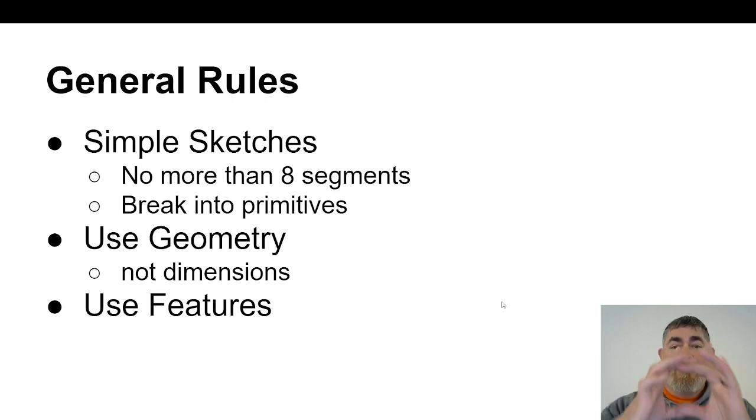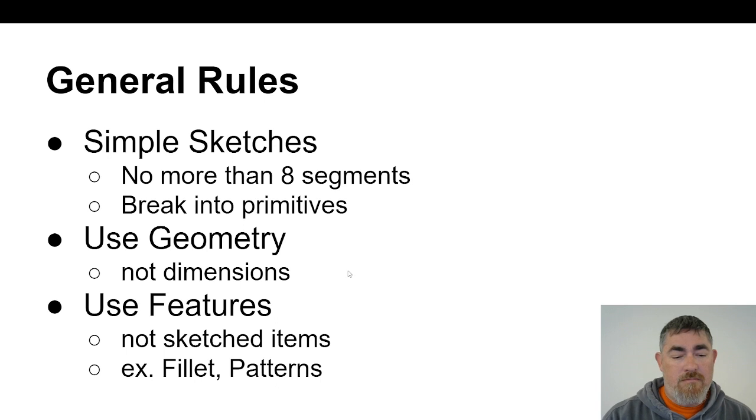Same thing with hole. Don't just extrude a circle, use the hole command. Now you have options to add chamfers, counterbores, threads, and not just to make an exact size, but make it a clearance size based on the standard. So instead of making a 1/4 inch hole for a 1/4 inch bolt to go through, you make it a normal tolerance. Now it's 0.266, so that gives that a little bit of clearance there, and it's a better product. So, all right, and that's basically the general guidelines for what is design intent and how we use it in general.